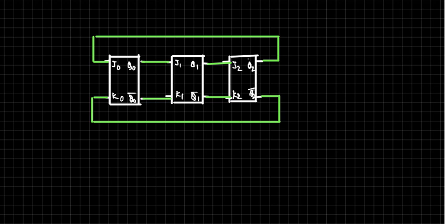So this is all about simple counters. Alright, is this clear? The analogy would be the same, the procedure would be the same. You will have to analyze step by step, state by state, and you just need to look at how they are connected: the uncomplemented to the J, complemented to the K, or in the D case, it's connected straightforwardly in the ring way.